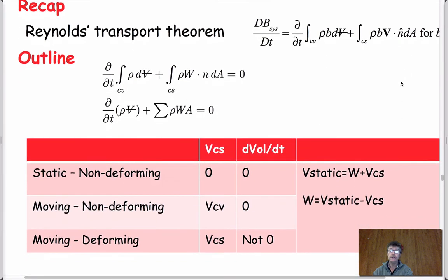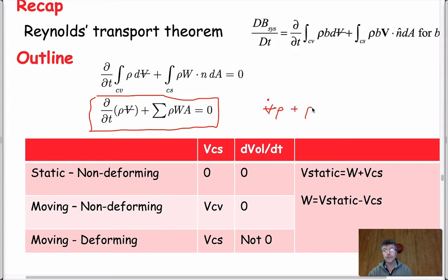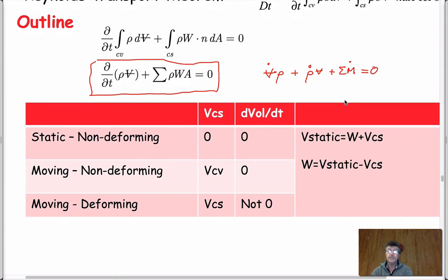What else? Well, so conservation of mass. We talked about the sign convention, which is, I guess, this. We've written it slightly differently, but it ends up being the same, which is rates of change of volume times density, rates of change of density times volume, mass flow rates equals 0. We have to be a little careful. I guess the only thing we need to know is that this mass rate of change is equal to a mass flow rate, so it's a density times an area, and it's multiplied by this relative velocity. This relative velocity relative to the moving boat.